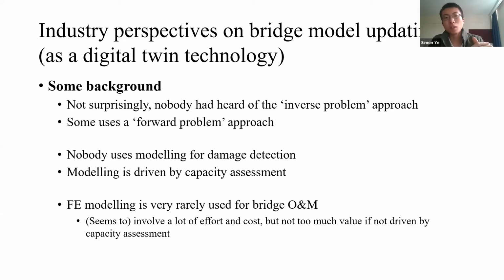For example, they use laser scanning to measure the geometry. They do some material testing to have some understanding of the material properties. And in terms of boundary conditions, we can probably do some visual inspection to see if the bearings are working or not.